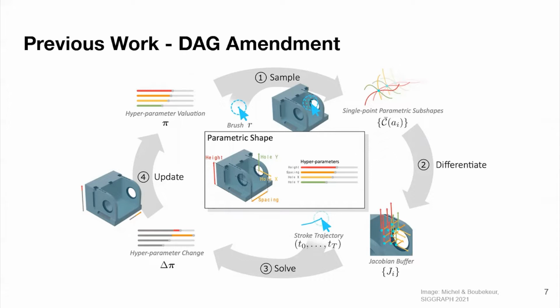More recent work in Graph last year focuses on models that do have a program associated with them, specified as a DAG of CAD operations. Users can inverse edit this using a brush by dragging on the mesh and specifying how they would like an area of the mesh to change. This uses pre-authored models and a finite difference-based automatic differentiation, and can even handle very generic edits that include topological changes through Boolean operations in the program.